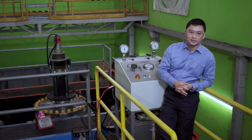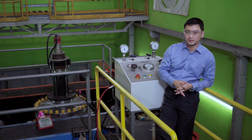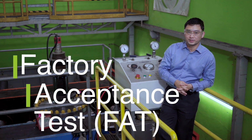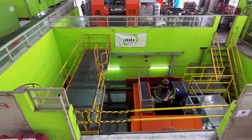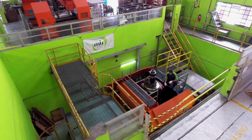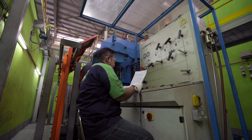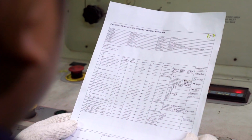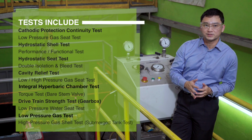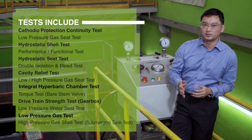My name is Andrew Pang. I'm the head of engineering at MIR-Valve. The valve that we're testing beside us today is the 20-inch Class 300 top entry subsea ball valve. It's got a forged body and metal seats. The client is Sapura Offshore and the end user is Brunei Shell Petroleum. Sapura Offshore has chosen to put this valve through a series of tests lasting 5 days. They can be categorized into these categories: shell tests, seat tests, drivetrain tests, and several supplementary tests that the client has chosen to do.